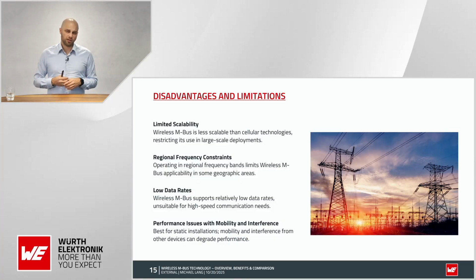The frequencies I mentioned, the sub-gigahertz frequencies, have one big problem. They are not usable worldwide. So the 868 megahertz are mainly usable only in Europe, and not, for example, in the US or in Asia. There you have different frequencies you can use in sub-gigahertz applications. And this is something you have to keep in mind, that it cannot be used worldwide compared to Wi-Fi or Bluetooth, for example.